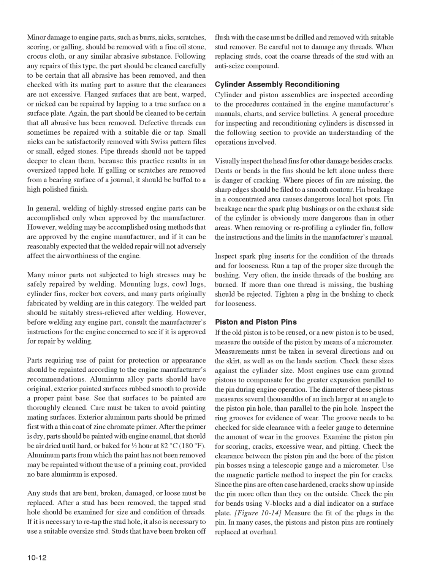Many minor parts not subjected to high stresses may be safely repaired by welding. Mounting lugs, cowl lugs, cylinder fins, rocker box covers, and many parts originally fabricated by welding are in this category. The welded part should be suitably stress relieved after welding. However, before welding any engine part, consult the manufacturer's instructions for the engine concerned to see if it is approved